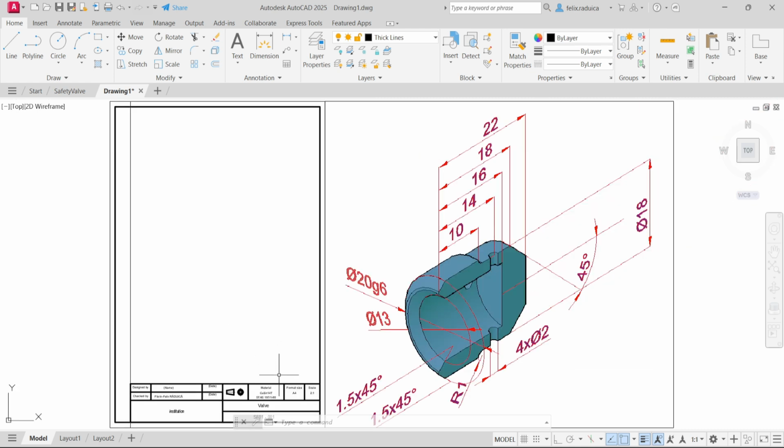So with the information filled in, we can move on to drawing, but also we can consider updating it as we draw. So this is an A4 sheet of paper, and the scale will be a 2:1 scale, an enlarged version of the part due to its small dimensions. So the overall size of the part at 2:1 scale will be 44, 40, and 40 again.